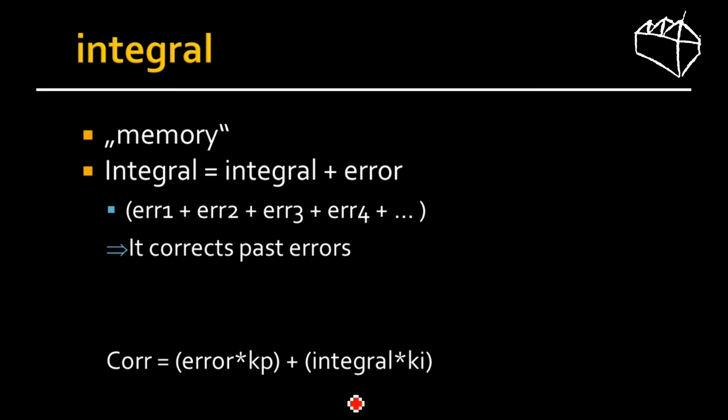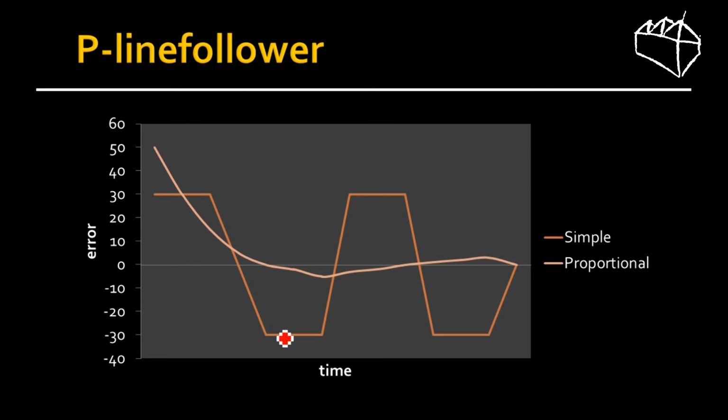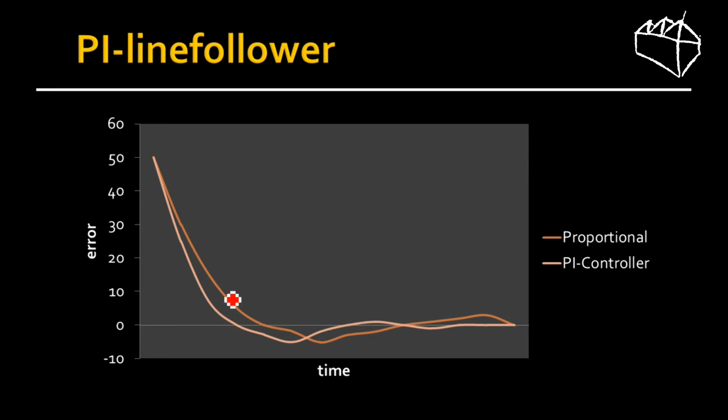What that does is, if you switch it correctly, you can prevent your integral from overshooting, because as I've told you, your integral gets higher and higher the longer you stay on this side. So let's say the integral here is now 0, and then 50, 80, and it gets higher and higher until your actual error is 0.